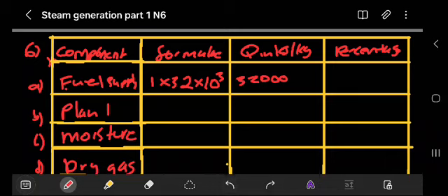The mass of the steam, we know that we have the mass of the steam. It was 8 into H4. H4 was 3148 minus H1, which is 188. We put that on our calculator. What is the value we'll get?